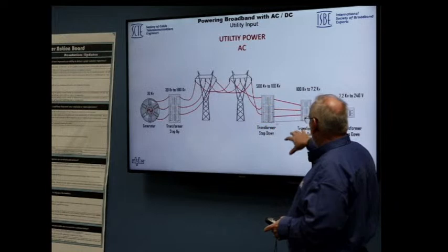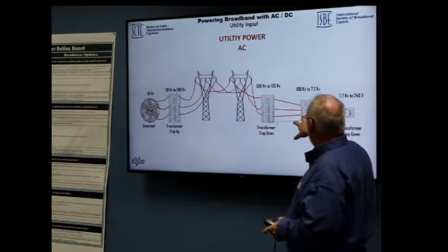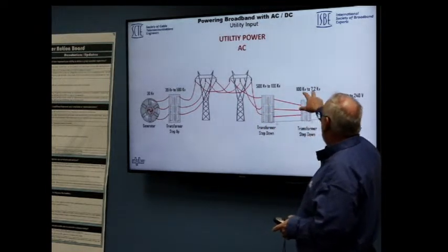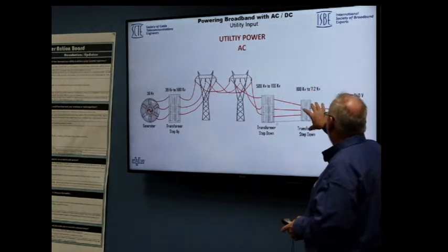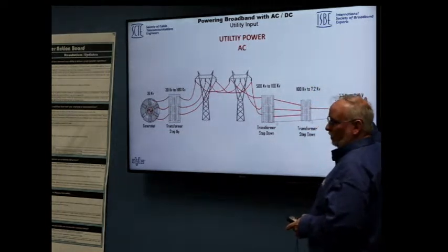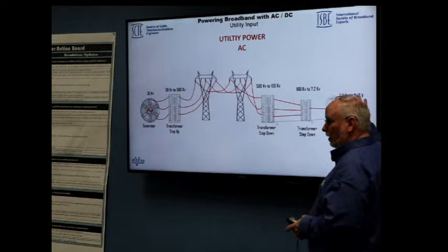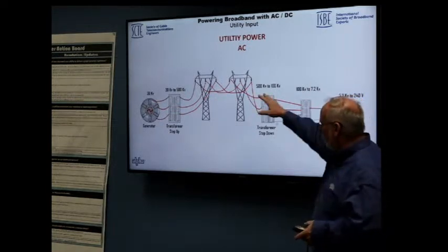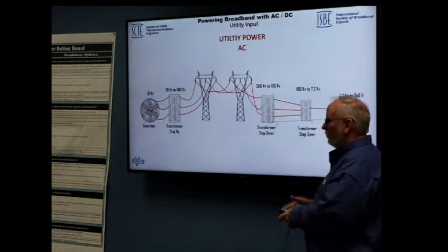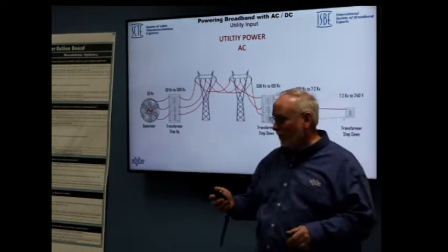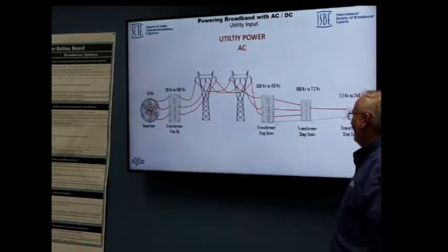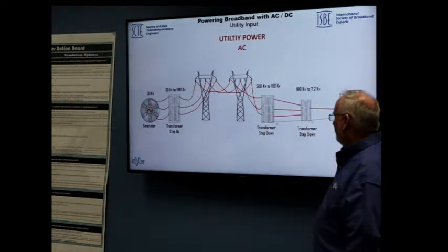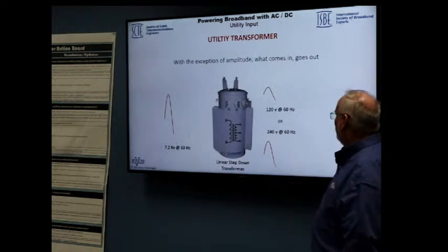And then finally a smaller substation, or could be an integrated transformer, to break it down to between 7.2 and 16 kV. Then it reaches the outside of your house or the outside of your power supply, and it gets converted to what they call low voltage, which is 120/240. We don't call that low voltage. So it's pretty simple.